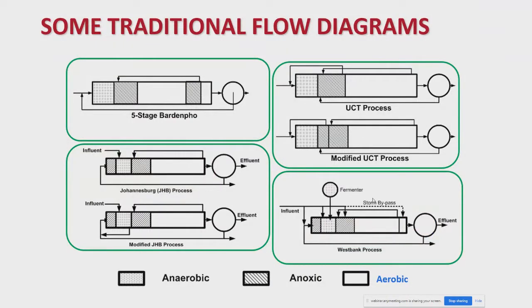Here we ended up with a process where the anaerobic zone is up front, and the requirement that I specified at the time is that we have an anaerobic zone with no oxygen or nitrates coming in. The idea was that nitrates will be reduced in the process to a low level so that there would not be a lot of nitrates in the RAS.